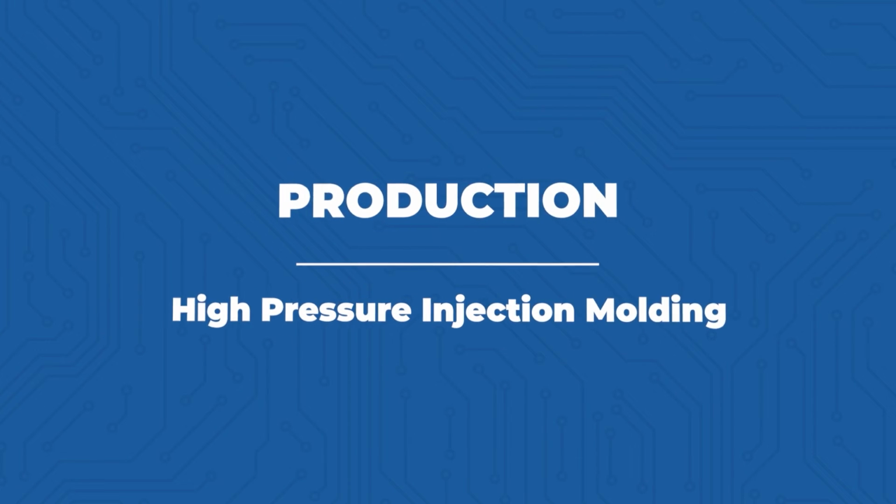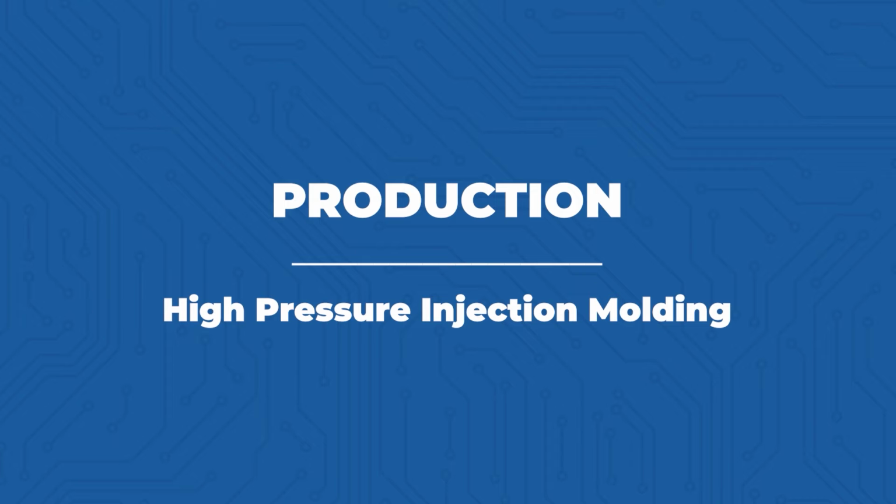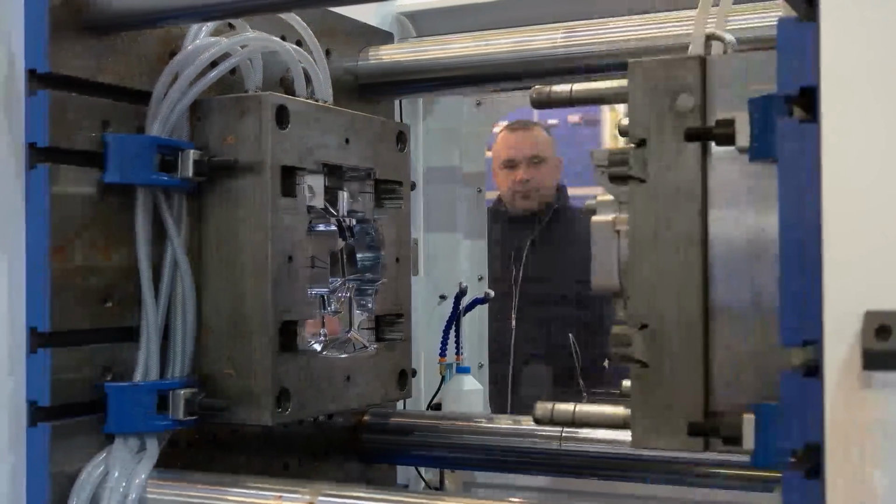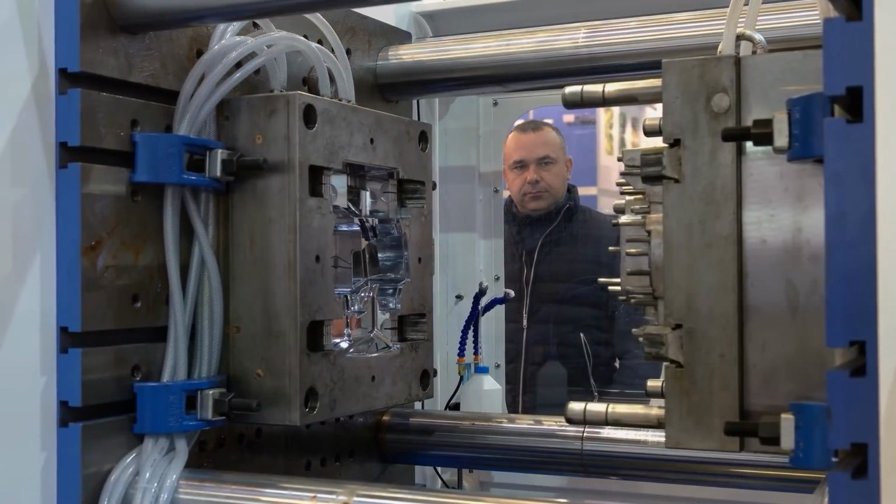Now, for production, it's a totally different story. For production of custom plastic parts, you're going to use high pressure injection molding. This is a really old technology: a mold made out of metal, typically steel, but lower cost ones can be made out of aluminum, that has a cavity inside of it, and the cavity is the shape of your part.